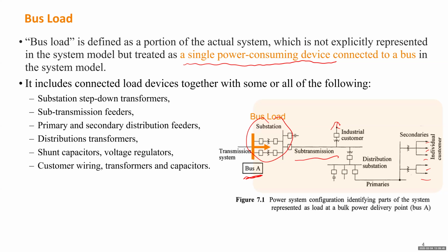Okay, so when we talk about voltage control and voltage stability, we'll use one example to show you that, compared to just aggregating everything in this area by a very simple element, the original topology of the system, considering transformers and controllers, can give very different results. Sometimes you may want to keep the transformer and voltage controller in the model. You don't want to reduce those by simply a load device.